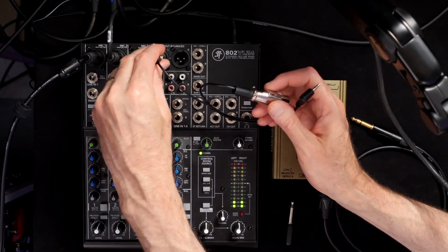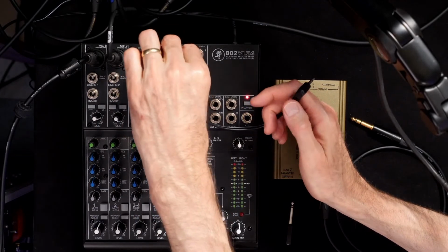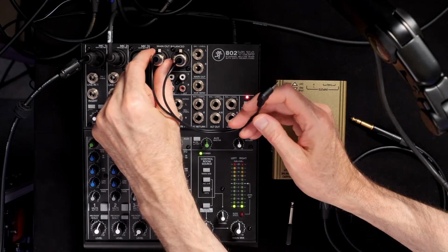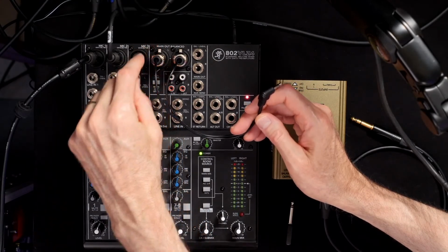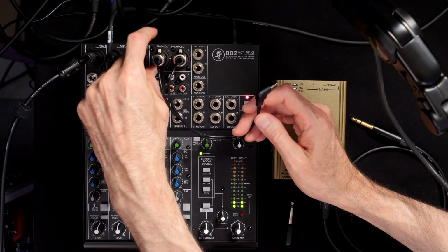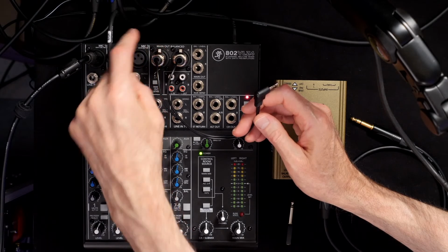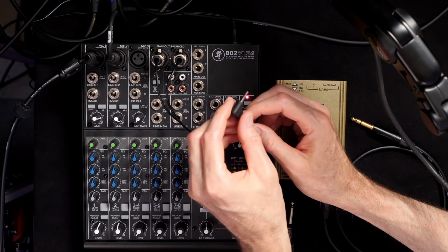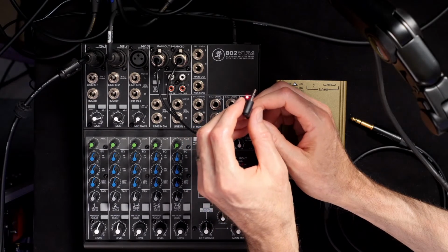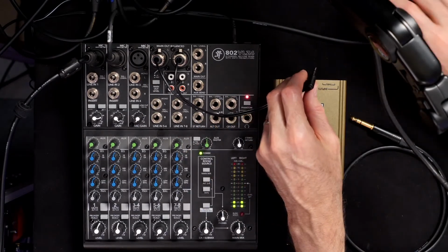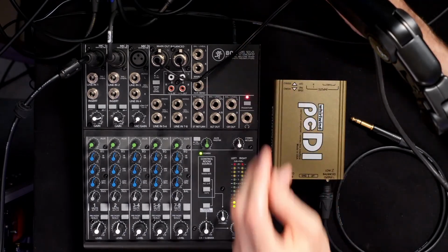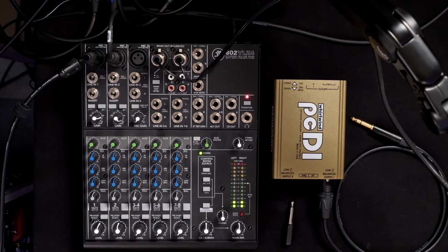And what I'm going to do is go ahead and demonstrate what that sounds like so you can hear what happens. What's actually happening here is it sounds like it's taking the two audio lines from one of the connectors and putting those on left and right here and then ground on the third one. And what that means is that the audio you're getting into the ATEM is actually inverse polarity.